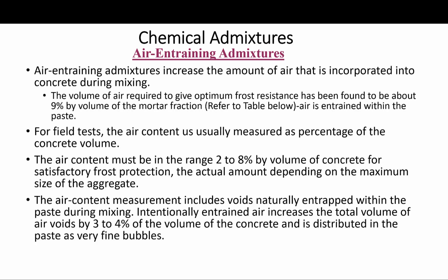Air-entraining admixtures increase the amount of air that is incorporated into the concrete during mixing. The volume of air required to give optimum frost resistance has been found to be about 9% by volume of the mortar fraction, as I will show in the next slide. There is a table, I will show it. Although the air is usually entrained within the paste fraction, when we calculate the air volume, it is based on the mortar or the concrete, as you will see.